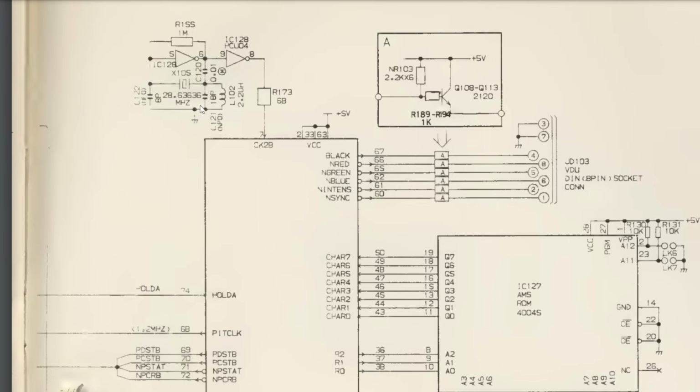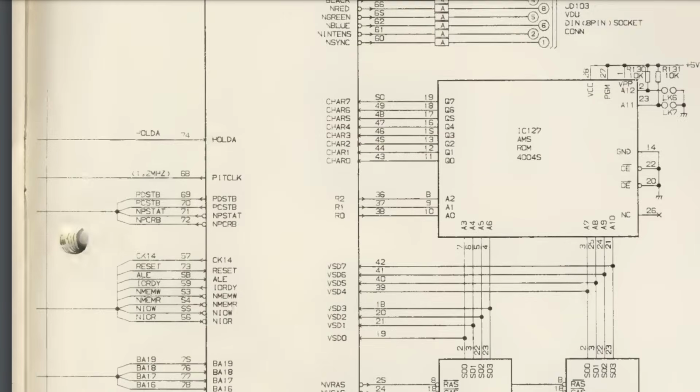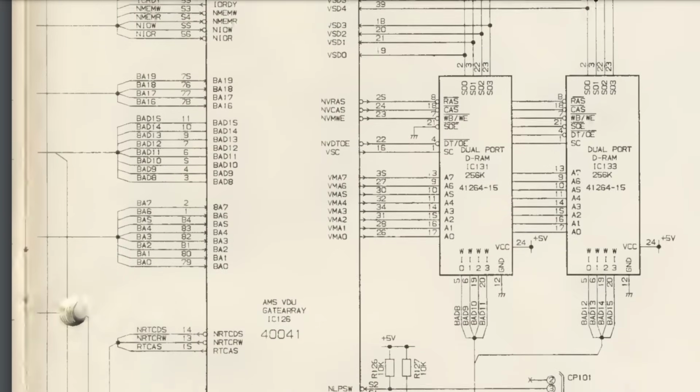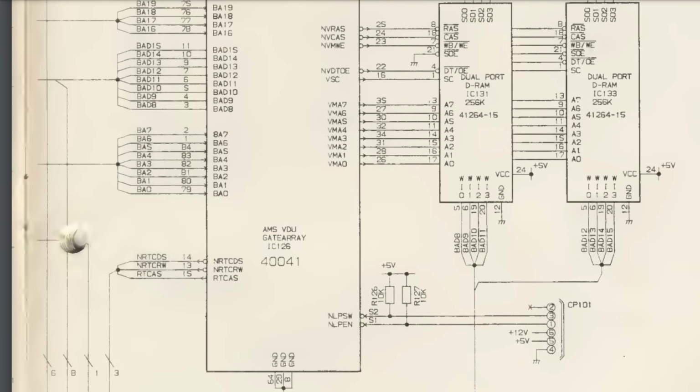And we can set it up to fire an interrupt at precisely the same place every single frame, really down to the pixel. The problem is that the thing that's going to respond to that interrupt is the CPU, and unfortunately that's just on a different crystal, so it's going to respond on the next available CPU cycle.